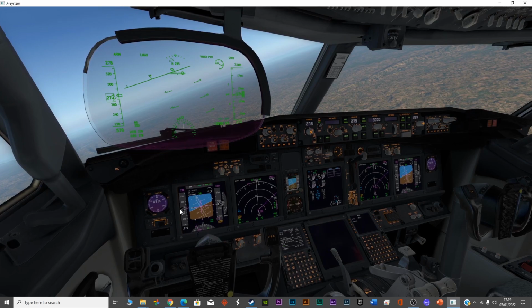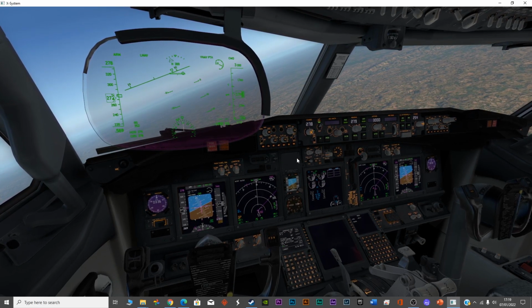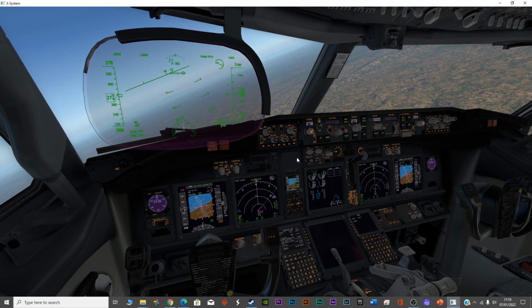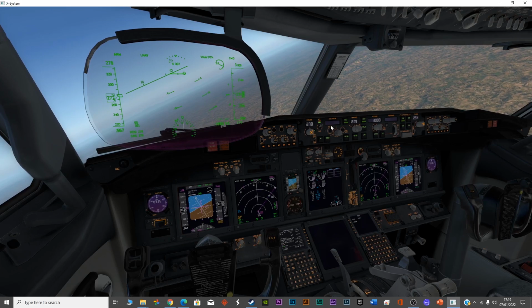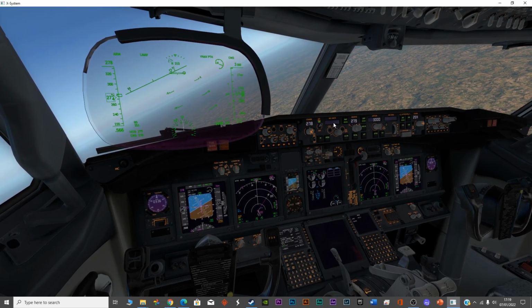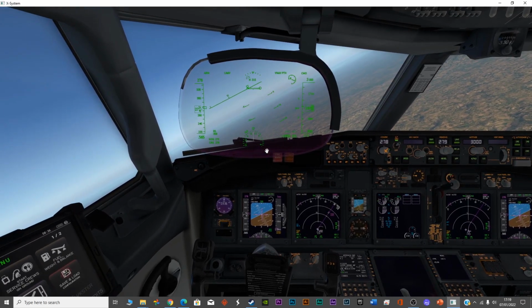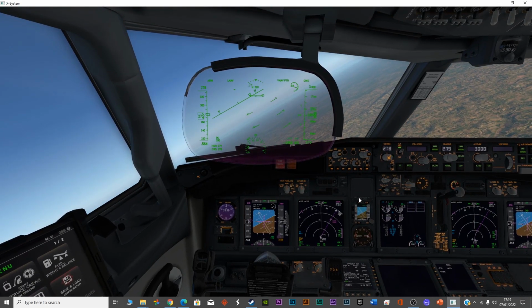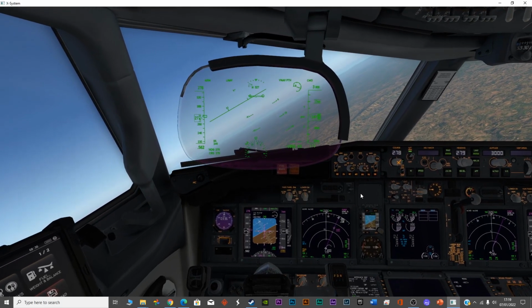And flaps, I'm not extending the flaps, but as soon as I'm near the runway, I will start to do that, and along with the gears I will extend the flaps to 40 degrees, and during the landing I will keep the speed at 140 when I will disengage this VNAV option. So this was a quick check through the approach and landing procedures.